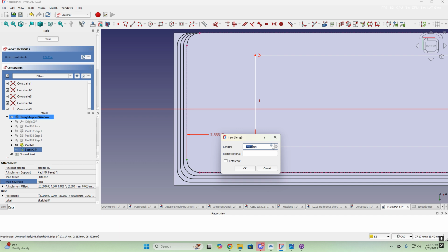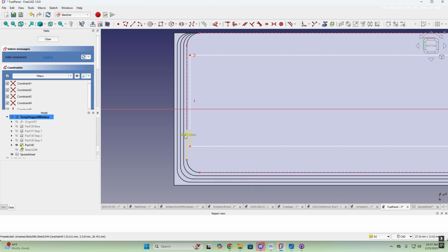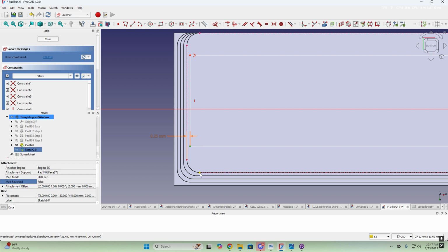And instead of typing in a dimension here, we're going to click the formula button, and then I'm going to put 2 brackets. Going to click spreadsheet, and then I'm going to hit window, and you see all the things from the spreadsheet are now showing up here. What I want is the width inset. Hit OK. You can see that puts in 2.5. That pulled that right out of the spreadsheet. You can see this dimension is orange because that means it's a calculated or formula derived value.